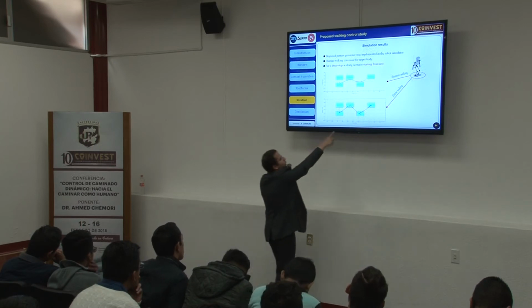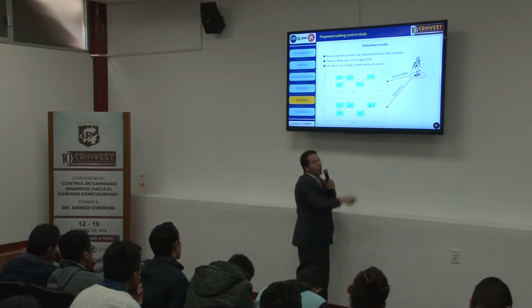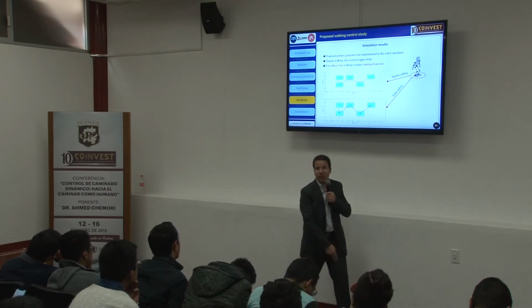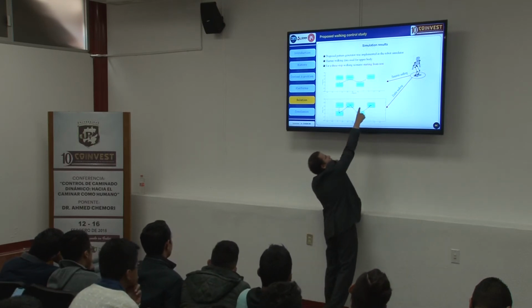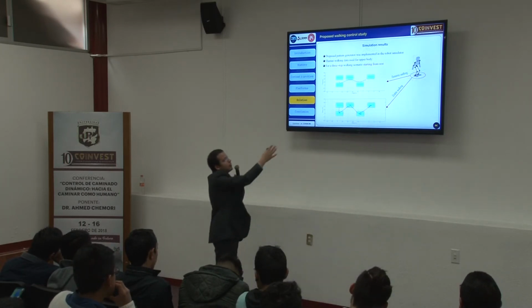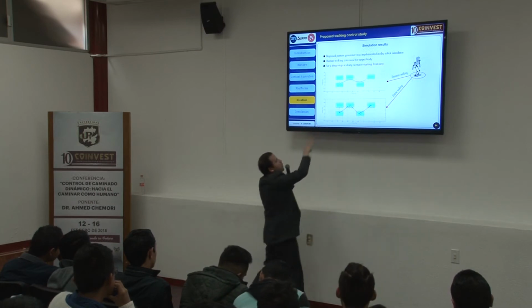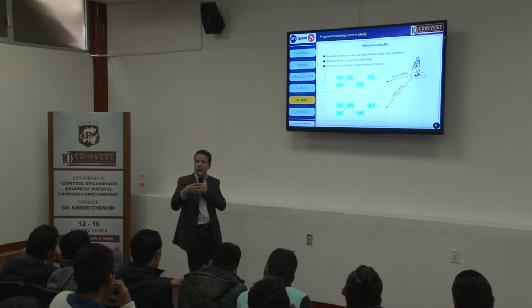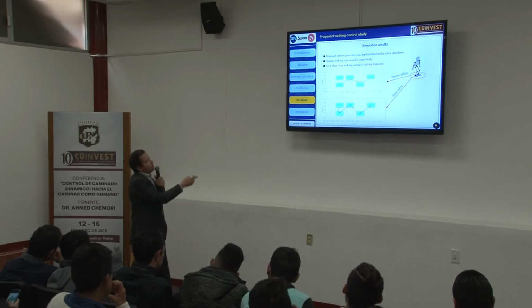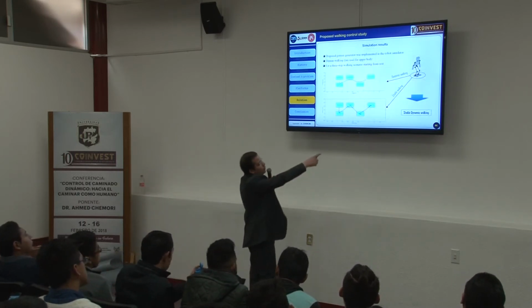So the blue one is the single support phase, so it's still inside. And the red one is the double support phase, so it's also still inside, because the polygon of support in the double support phase will be this. Nice. And it's dynamic walking. Why? Because the projection of the center of mass, the first picture, is outside from the polygon of support from time to time. So this is the obtained result, and we had the stable dynamic walking.